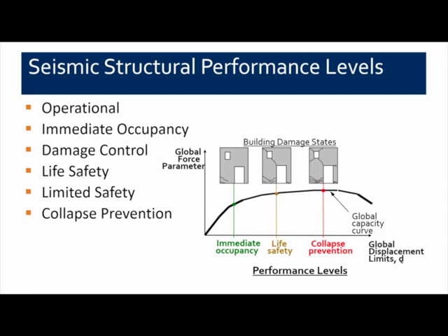The most common level of performance that we use for design is what we call life safety, and this would anticipate some level of damage to the building that would not be sufficient to keep people from leaving the building after the earthquake. We would want to make sure that everybody is safe within the building.